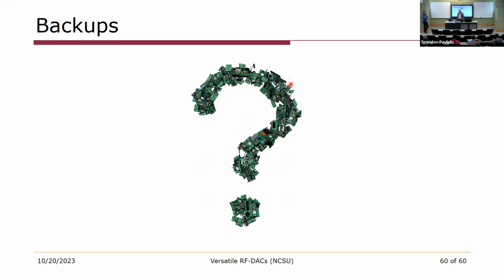Regarding the switch cap PAs, you did mention that it gets better with CMOS scaling, mainly because you have lower switch resistance and capacitance overall, it just goes down. From a switch perspective, going to a lower technology would probably enable you to go to higher frequency, if you just look at the switch alone. Yeah, if you look at the transition, the earlier stuff was done in 65 nanometer and the later stuff is done in 22. Now, fundamentally, we probably could have done some of this stuff without going to 22 to get 30 gigahertz performance.